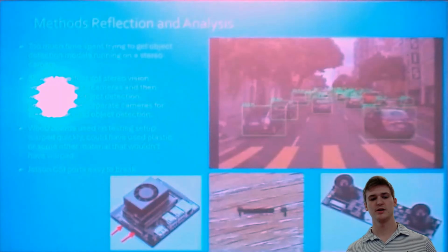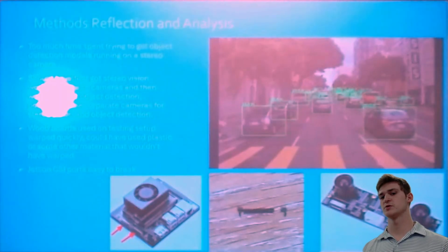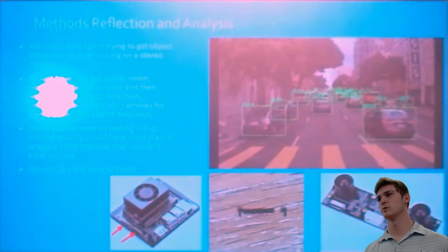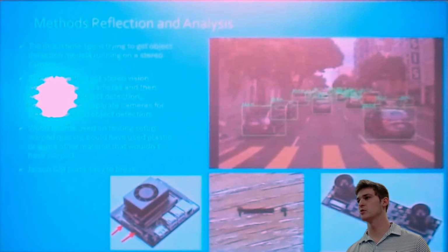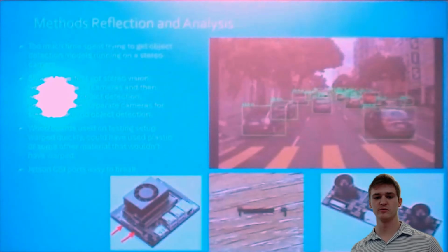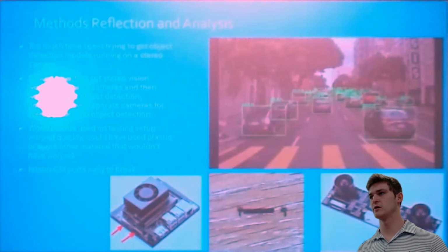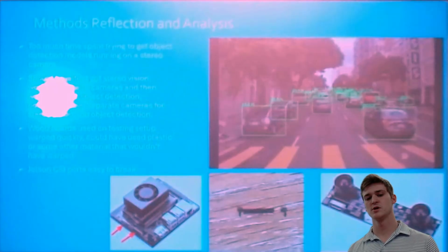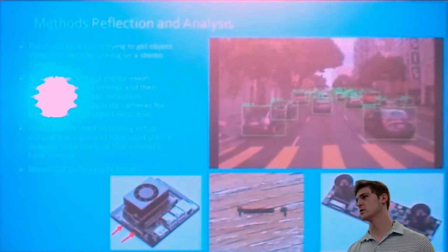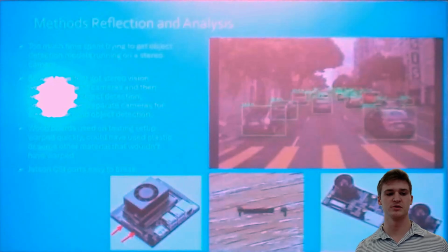I tried to get the object detection models from Edge Impulse running on these cameras, but the expected resolution from Edge Impulse was way different than the input resolution of the cameras, which caused a lot of problems. In reflection, I could have tried to get the stereo vision working on these cameras while just running the object identification on other cameras and used the two of those in combination.